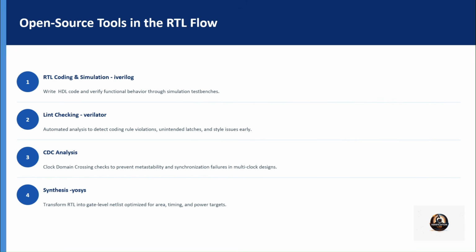We recently discussed RTL code. Now we see simulation. What is simulation? Before moving forward, you need confidence that your RTL code actually works as per your functionality. This is where simulation comes in. By using tools like iVerilog, Verilator, or commercial tools, you can execute your HDL code with test inputs and observe the output.